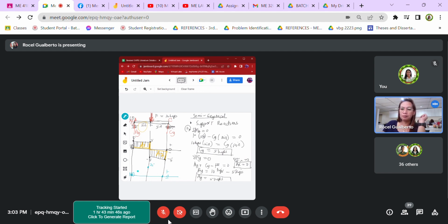Then you connect. How do we connect? Your reference is the shear diagram above. This is a horizontal line. A horizontal line is 0 degree. This one is also horizontal, so 0 degree. They always go in sequence: 0, 1, 2, 3. 0 is a horizontal line, 1 degree would be a slanted line, 2 would be a curve, and 3 is another curve.